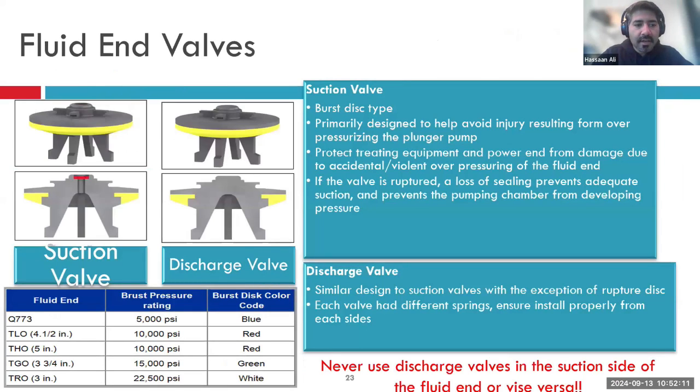So these are spec'd to a point where they will open at a certain pressure only. They will not open at a low pressure, and they will not open at a high pressure. There is usually a spring in between that you can change, and you can either increase or decrease your opening or closing pressures. Is this attached to a software application? No, it's totally manual at this point of time. Most of the reciprocating pumps are totally manual.